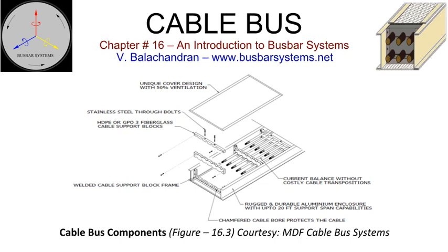The aluminium sheets and extrusions can be anodized or powder coated with epoxy paint for additional resistance to corrosion. The preferred thickness of the aluminium sheet is 3 mm, 1/8 inch. In certain extremely aggressive corrosive atmospheres, the enclosures may be fabricated from stainless steel SS304 or SS316. This will, however, be expensive. Enclosures can also be made from hot-dip galvanized after fabrication, HDGAF, steel sheets. It is preferable to install stainless steel, grade SS304, fixings for all assemblies of cable bus.